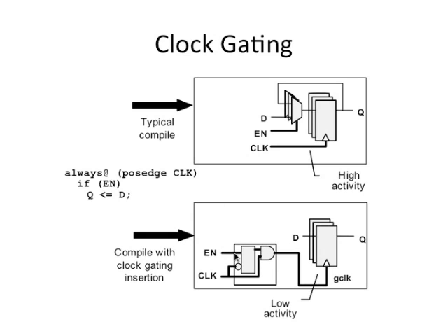So your clock gating circuit will be something like this. Typically, when you have buses, 16-bit, 32-bit, etc., all the flops in the bus have their clocks connected, and there will be one clock gating circuit in the clock path, which gates the clock and then connects to all these other flops.